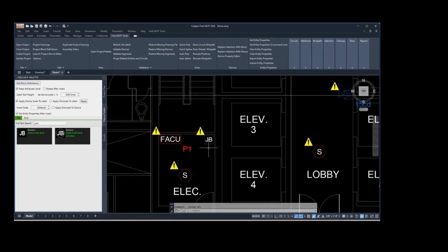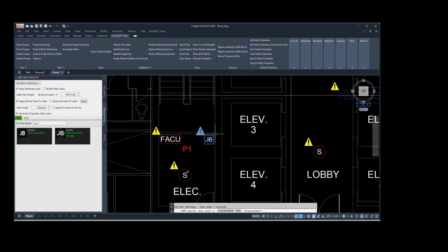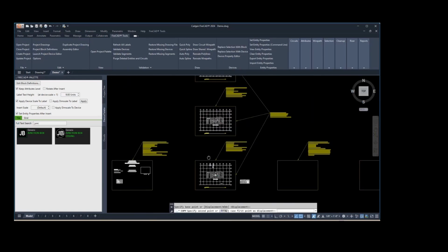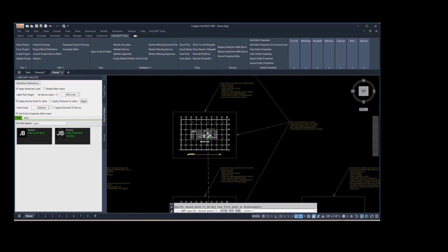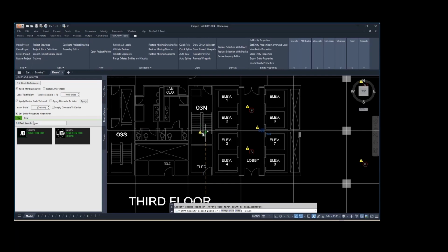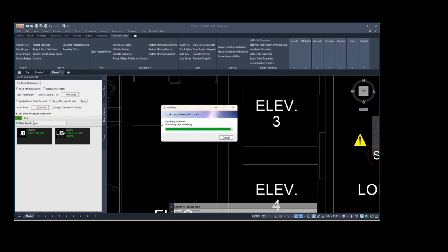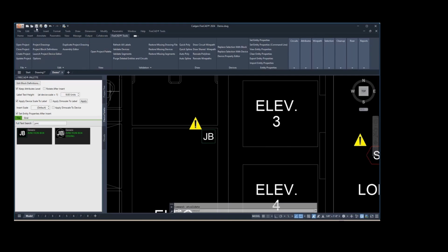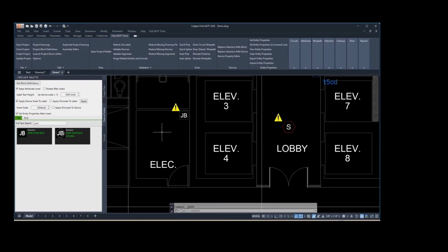and now I'm going to copy this by using the ordinary AutoCAD copy selection. I'm going to line it up on the second and third floors with that corner of the electrical room so that I'm going to have 3 junction boxes, which I can use for the place where I'm going to run my riser. I'm going to validate devices and then save my drawing. We get very few crashes that are due to FireCAD. It's possible once in a while.